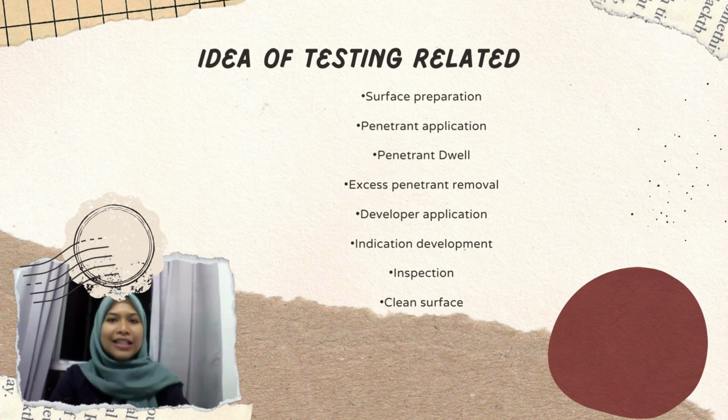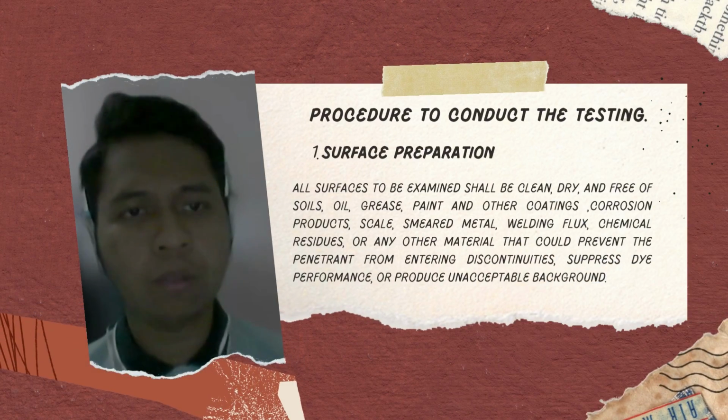The steps of the testing are as below: surface preparation, penetrant application, penetrant dwell, excess penetrant removal, developer application, indication development, inspection, and clean surface.